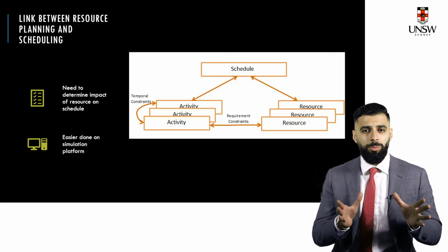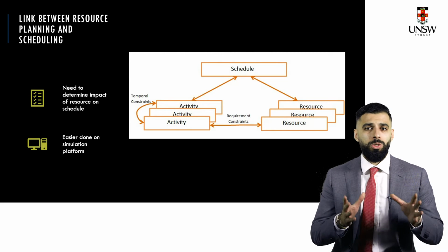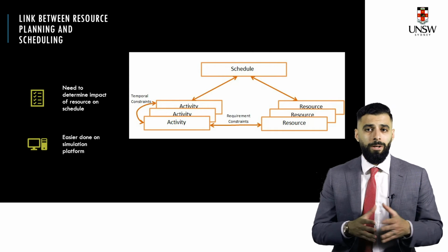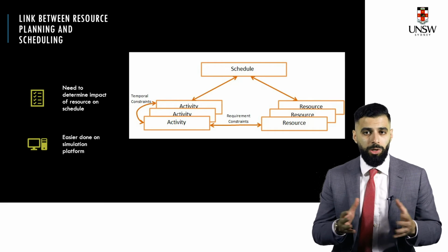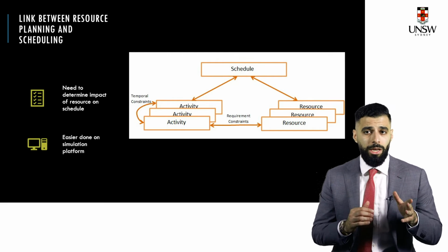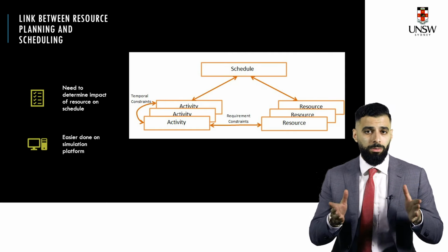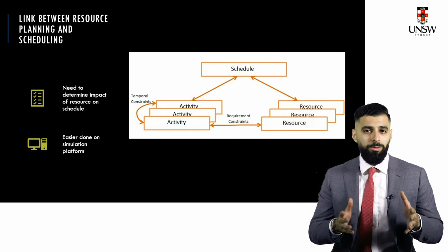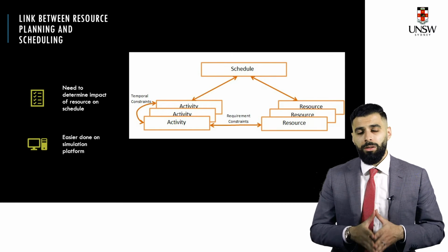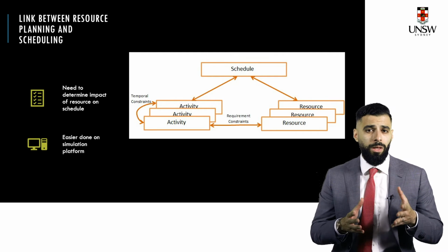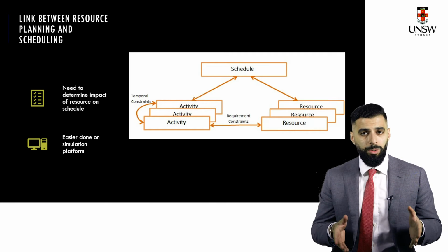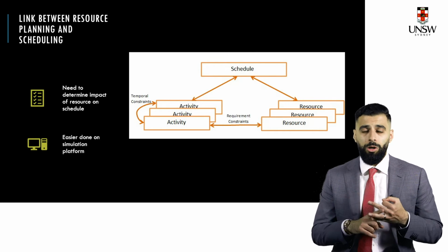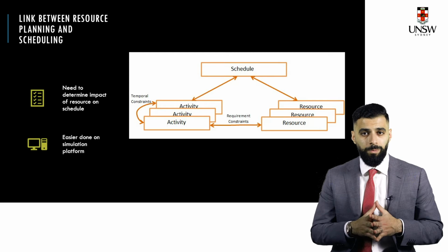Let's have a look at an example to make it clearer. Suppose you wish to simulate, using 4D BIM, the concrete pouring of a concrete slab you have on site. First, your concrete slab requires 4 workers, 12 meters cubed of concrete, 40 meters squared of formwork, and 3 tons of steel. You know that the construction activity associated with this slab is formwork placement, steel fixing, concrete pouring, and curing.